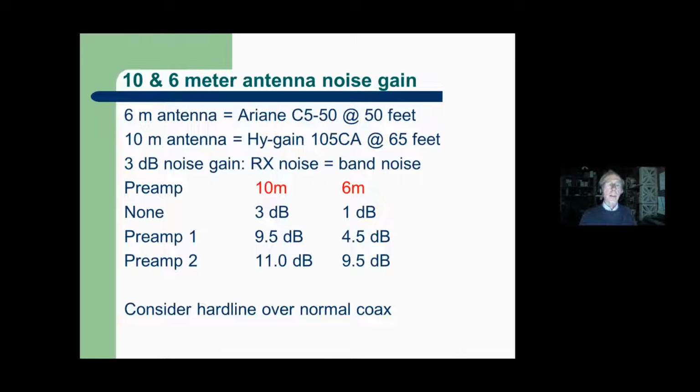We've talked about now, what do we do on 160, 80, 40? We turn on the attenuator, so band noise isn't really so dominant running the AGC, but how do we know when to turn on the preamp? I call this antenna noise gain.